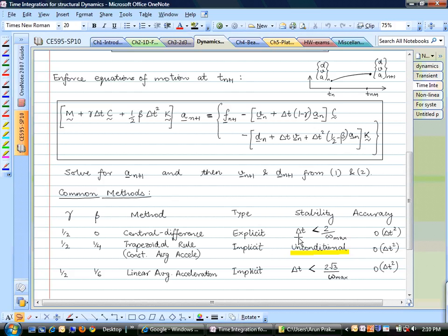methods to be stable. But when you use Abaqus explicit, you may not have to worry about what this delta t is, because Abaqus will automatically calculate this quantity, and it will choose a time step that is smaller than this.